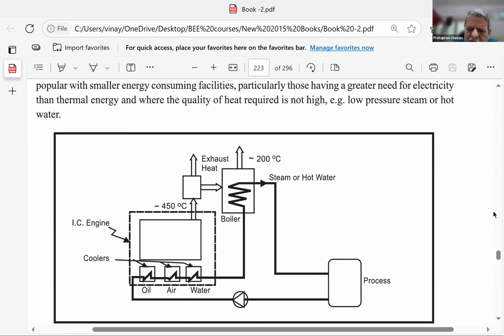and generate power. But normally, these cogeneration schemes are for very small purposes. MSME type of factories where they have one large IC engine but not large enough to produce power on the steam. So the steam, which is a secondary generation or cogeneration, is normally used for factory internal process purposes. After cooling down in the process, the heat is taken by the process and the cooled-down condensate goes back through these coolers and goes to the boilers.